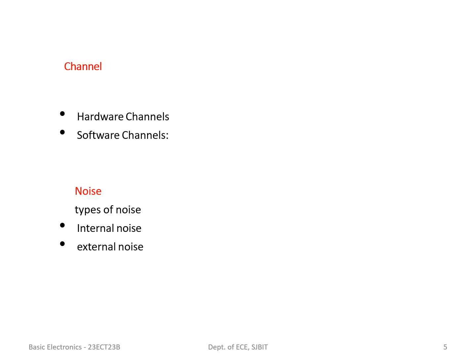Coming to the hardware channel, it is also called line communication. These channels are man-made structures which can be used as a transmission medium. There are three plausible implementations of the hardware channel: one is the transmission line, the second one is the waveguide, and lastly the optical fiber cables. Transmission lines are twisted pair cables used in landline telephones, and coaxial cables are used for cable TV transmission. Transmission lines are not suitable for ultra high frequency, that is UHF, transmission.